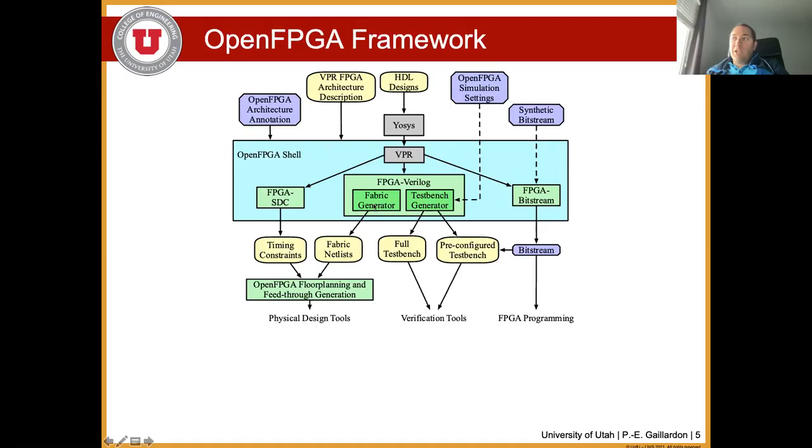So in order to do that, we had to complement the language from VPR with some OpenFPGA architecture annotations and more lower level descriptions compared to what VPR traditionally models. So we can do that all the way down to the nitty-gritty details of the circuit implementation. And we also support a complete test bench generator to validate that whatever fabric we generate along with its bitstream generation actually matches and is actually correct. So we can verify the complete fabric.